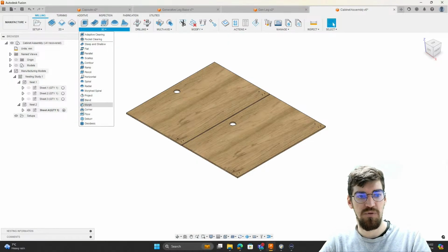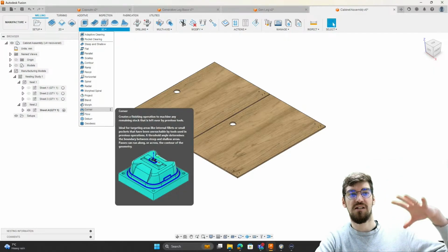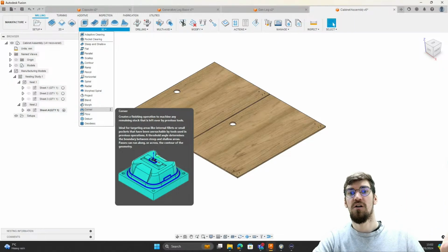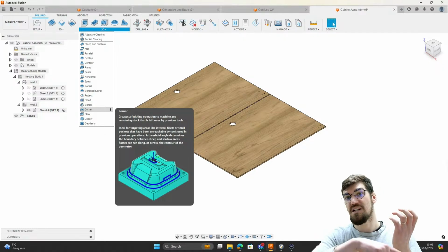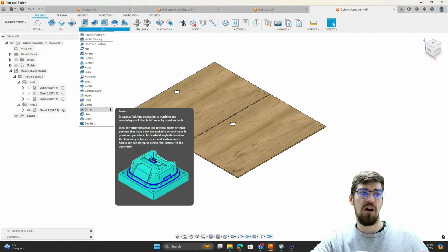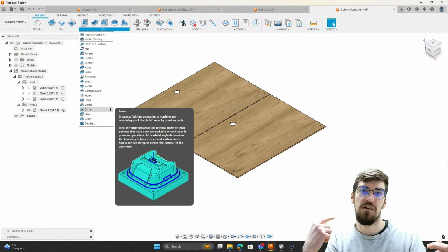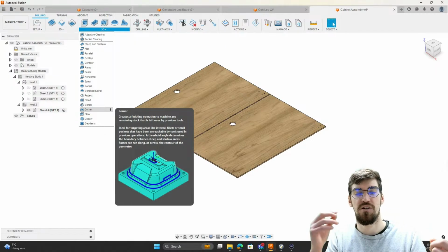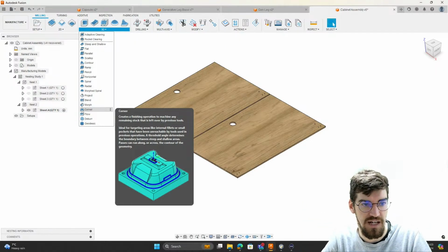Opposite, I suppose, to deburring, we've got cornering, which is going to allow us to say, well, if we've machined using a particular tool, we know that we want to finish off wherever that particular tool wasn't able to reach. If we've got a larger tool that we wanted to use for big clear out and a lot of roughing on the model itself, we then want to go in with a second tool and finish off any of the pockets, any of the corners that particular tool wasn't able to get to because it was a little large. So cornering is going to allow us to do that.